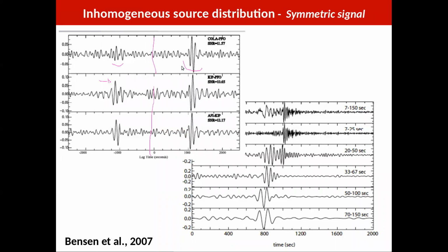So you can take only one part, or in the usual case, you can also find the average between these two signals, because the travel time information is the same, and it's the same medium. So you just cut this into 2, flip this onto this part, and average the 2 signals, and this will be your final results that you analyze.